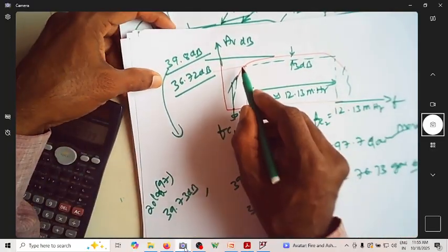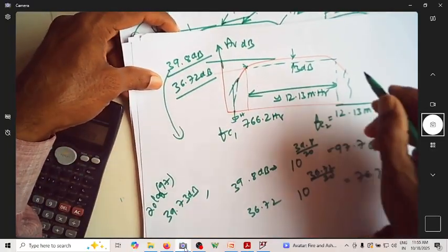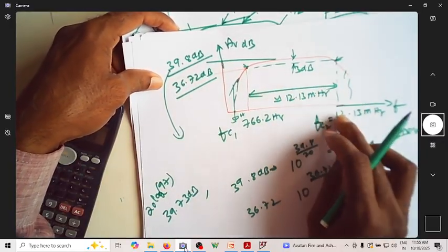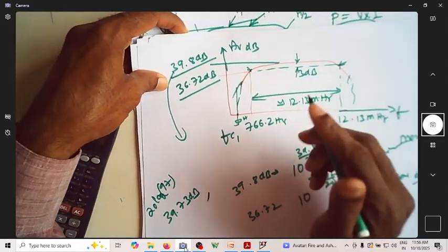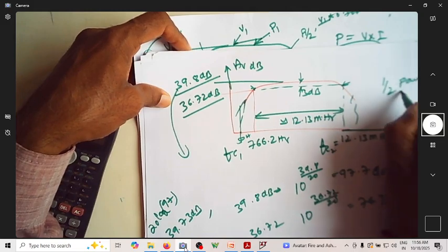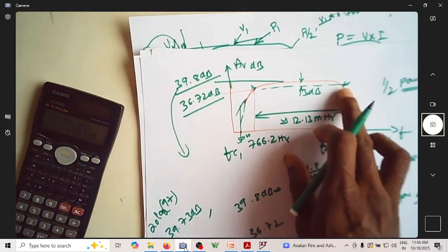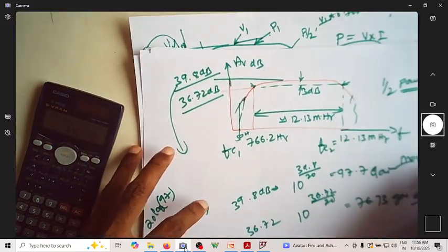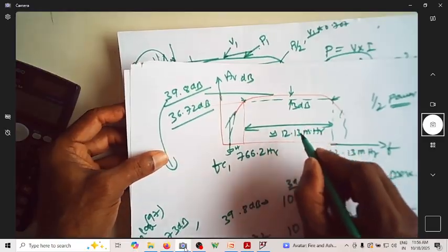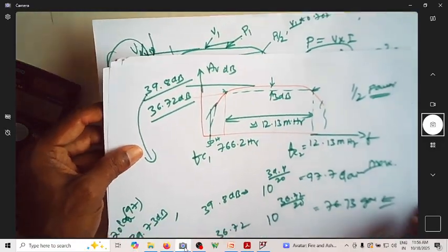So why are we using these 3 dBs? Because in electronics we have to demarcate some point where the frequency is said to be the cutoff frequency. So we consider the half power point as the cutoff point. If the power is less than half, we treat it as not a good signal. So that's why it is also known as half power bandwidth.